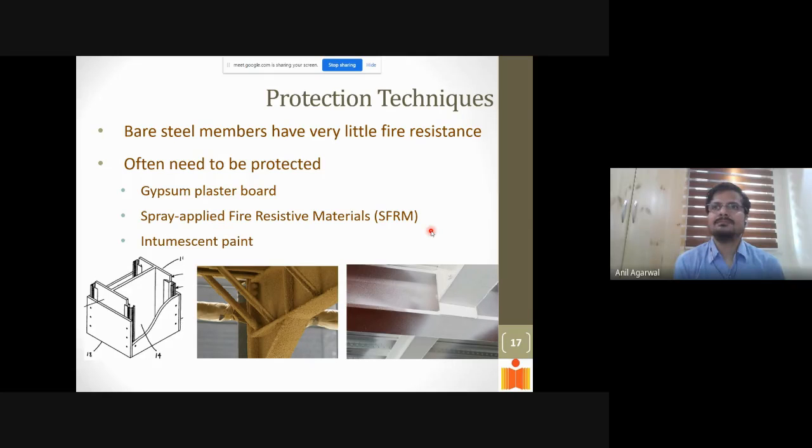0.6. Yes. So it depends. In India we take 1.5 as the factor of safety for dead load as well as live load. So you have to do 1 divided by 1.5, so it's approximately 0.67 for columns, let's say. Correct. So under service load conditions, you would typically have 67% of the design load.